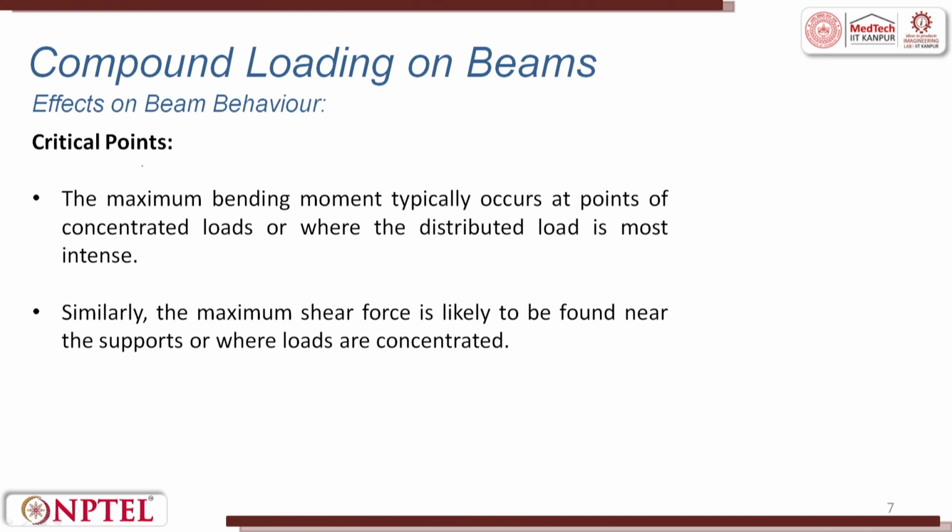The critical points to note: the maximum bending moment typically occurs at points of concentrated load or where the distributed load is most intense. Similarly, the maximum shear force is likely to be found near the supports where the loads are concentrated. So, two points.